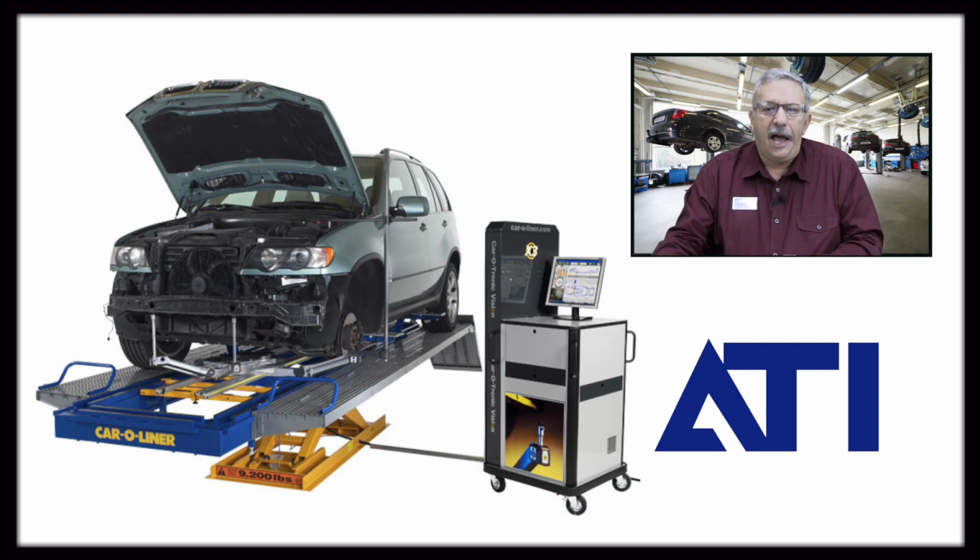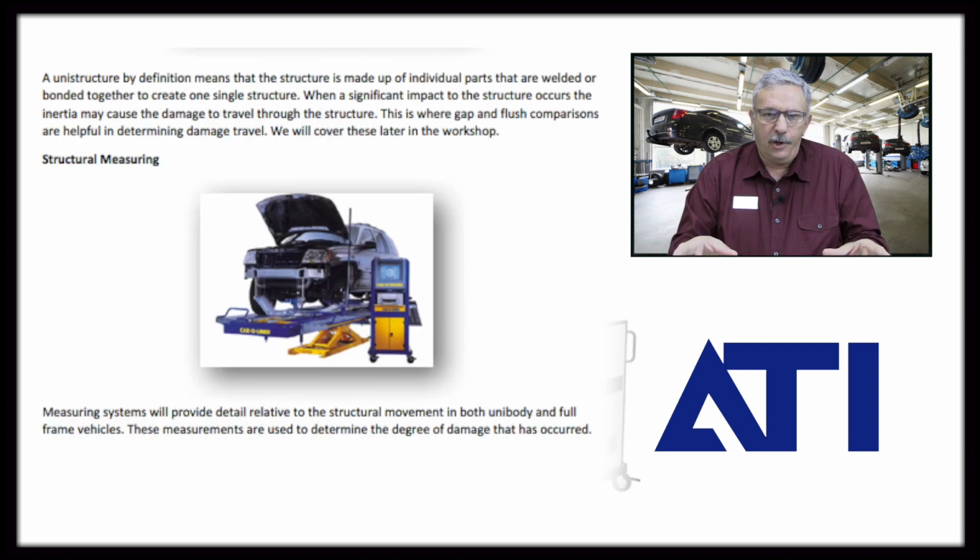That goes against a diagram set up for that specific vehicle, and it tells us how far out of tolerance the measurements are, which we're going to talk about more. That indicates to us the time required and the method that will be required to restore the vehicle back to the pre-loss measurements.